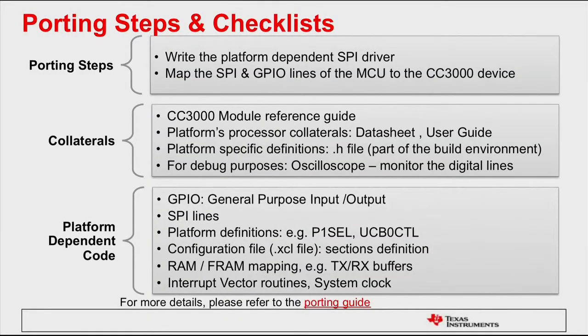So there's options there for you as well. Okay, let's go through a little bit on the porting steps that you would use if you were going to do porting. So the first things there are really writing a platform-dependent SPI driver, so what's specific to the hardware that you're using, and then mapping the SPI and GPIO lines to that MCU itself, so connecting those with CC3000.